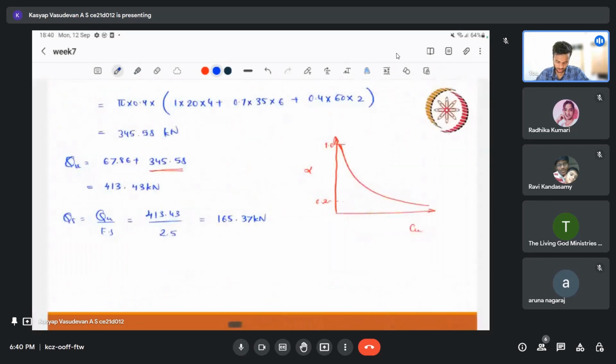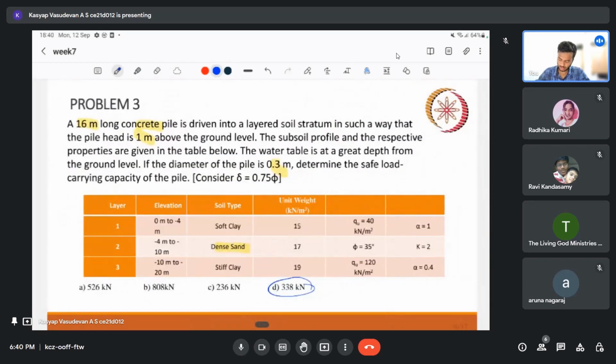Okay, so one thing that we are spoon-fed is that these values we can get directly from the laboratory, just after doing site investigation. For each layer we get samples using different site investigation techniques, and using those samples we get these values in the laboratory. This is done by the UCS test. This you can do by either triaxial or even direct shear test, depending on the problem.